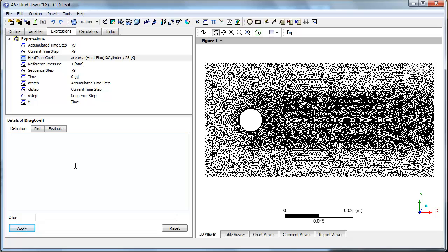First thing I need is the drag force. So I can use force underscore x at the cylinder. Again, I could find this using my calculator. And you see, this is how I learned the monitor points as well in CFX Pre. So there's 6 times 10 to the negative 9th newtons of force created by drag. Now remember, I've only modeled half of this, so I need to double that because I have 2 halves of my cylinder. So there's 2 times. Okay, and that is appropriately doubled.